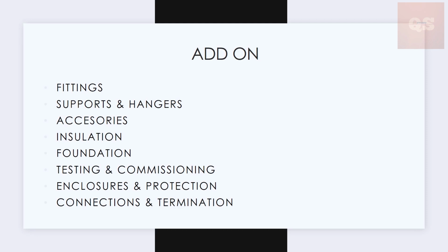So these also need to be included in your rate analysis so that confusion will not be there and you will not have a loss in your project, because if you miss out these fittings or supports and hangers, then it can cause an impact on the profitability of your project. So understand what is required for that particular item, what are the add-ons required for that particular item. For installing equipment, some panels, sometimes you will need a foundation to install it. So read through the specifications properly.